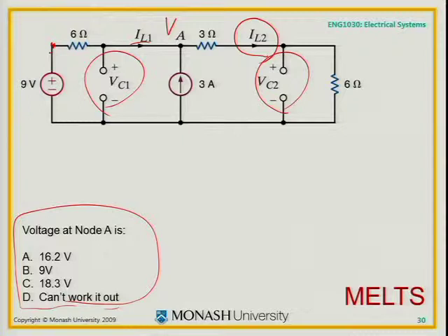So again, I hope you can make that separation. Once I've got the circuit in that form, it's not really about capacitors and inductors, it's can you do Kirchhoff's current law at a node. Once you've got the IL1, the IL2, the VC1 and the VC2, can we use some stuff about capacitors and inductors to calculate the stored energy?